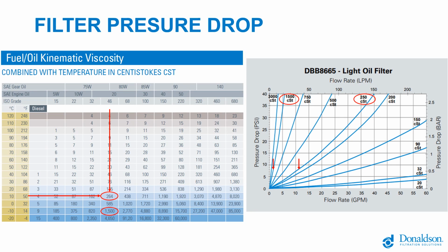For outdoor tanks, it's good to use the average January temperature. So if you go on any weather website and look up for that location what their average winter temperature is, high and low, and pick the midpoint of that. If it's an outdoor tank, that's a decent estimate for that minimum temperature you need to size for. If it's inside a shop somewhere and it's a heated lube room, you have a better idea of what the temperature is. But temperature is critical to figuring this out.